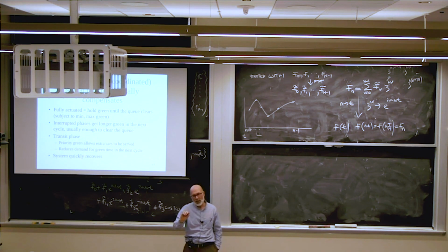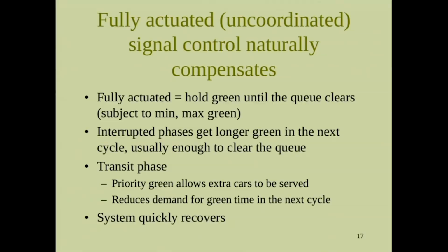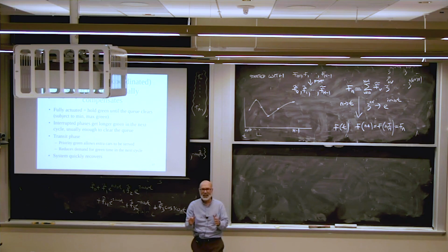So if we increase the sensitivity, then that'll detect a bike. But then the danger is it will also detect a car in the next lane over. So there's a trade-off there. If we want to detect bikes, we use a figure 8 configuration, and then we try to educate the bicyclists to ride right down the middle of that figure 8, and that's where you'll get picked up the most.